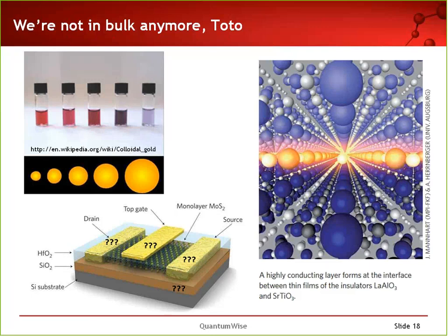Because look, you're talking about some sort of MoS2 molybdenum disulfide monolayer here, and you can see the individual atoms. But what about the atoms in the drain? What about the atoms in the substrate and the dielectric? You cannot separate the resolution in that sense, in that way. Those contacts will also be atomistic, and you have to consider that. You cannot just assume that they are some big slab of metal.